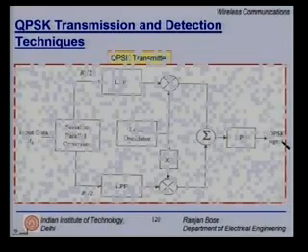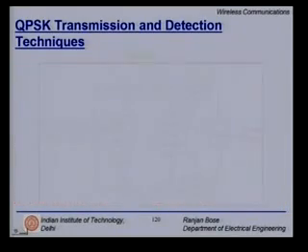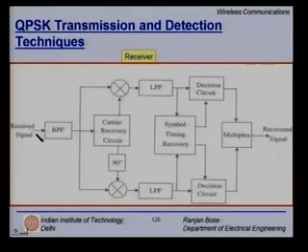If you have to do the receiver part, you have the received signal, band pass filter it, you must have a carrier recovery circuit as discussed before, in phase, quadrature, multiply, low pass filter it, also have a symbol timing recovery, decision circuit, multiplex, because you get from arm 1 the signal for one of the bits, and from the second arm the second bit, and for every symbol you get in, you get 2 bits out on this side.